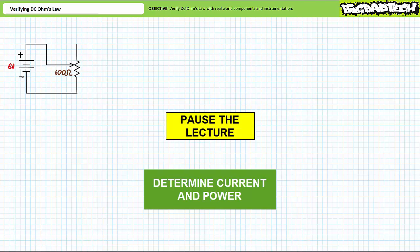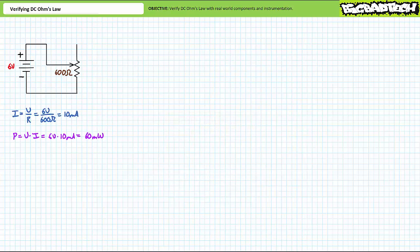By all means, pause the lecture and try this on your own. Express your answer using proper engineering format to the tenths place. If you're tracking, you should have obtained the following results. An application of Ohm's law demonstrates the potentiometer should draw 10 milliamperes of current. A subsequent application of the power equation demonstrates the potentiometer will consume 60 milliwatts of power, well below the 250 milliwatt upper limit. Let's build this circuit and see if our observations match our expectations.